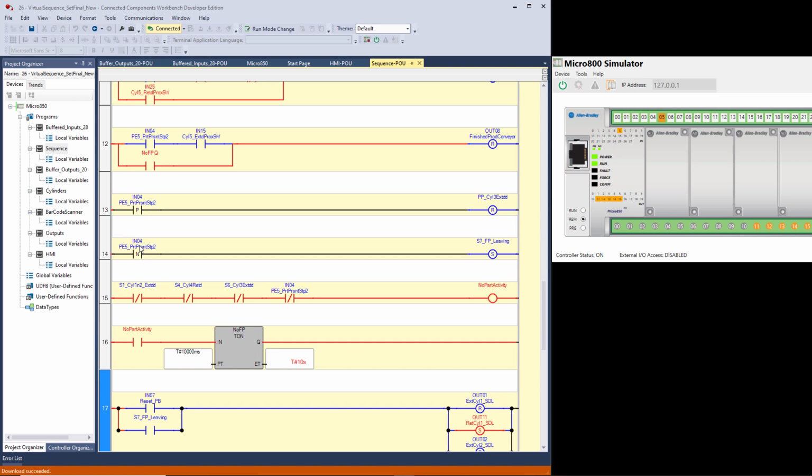In the case of a true if off here with a one shot instruction, then this rung would be true when the rung went false for one program scan. Same thing. Actually, this is pretty cool. We'll call it positive or leading edge of the pulse and the trailing or negative edge of the pulse.